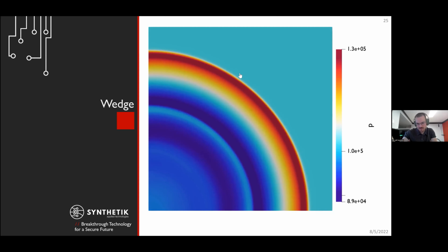The nice thing about BlastFoam is you can do that adaptive mesh refinement. So if you have a 1 kilometer domain and your charge is going off, it really is only going to be affecting a pretty small amount, and you can basically just watch that primary shock travel away. While you will get a lot of cells around that shock, relatively speaking, it's a much smaller cell count than if you were to refine the whole thing.